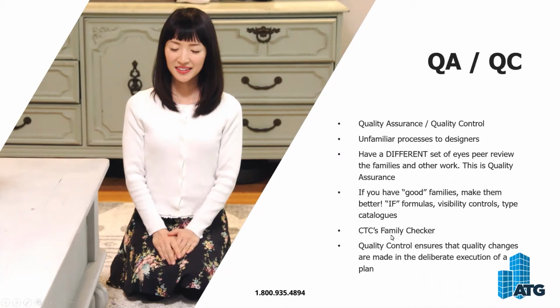So having something like a family checker to automate part of that process, and then just basically give you a checklist: get in here, set a reference plane, constrain the edge of this geometry to that so that it has an instance parameter that controls the length. I do those things, and in 10 minutes, I'm through with that family. So not 4 hours of investigating and trial and error with it. QA/QC, that's what it is. We need to start there too.